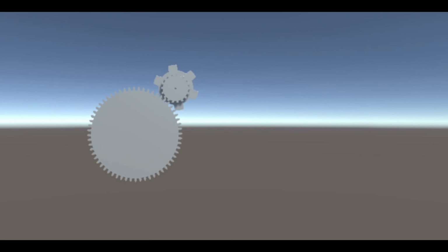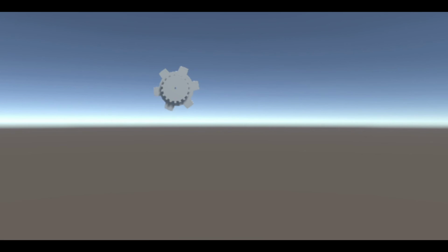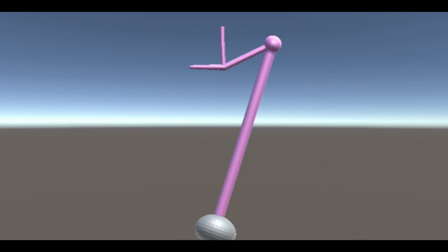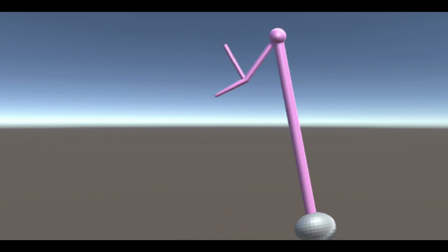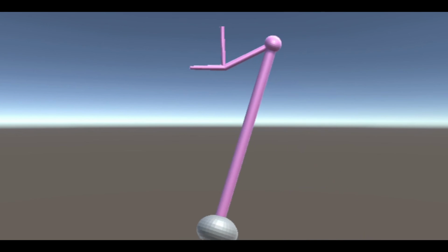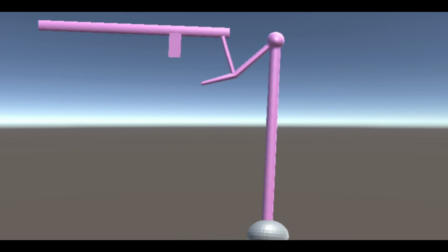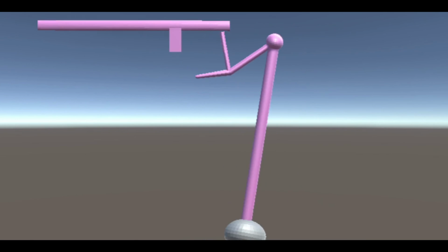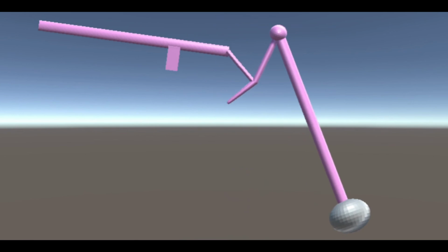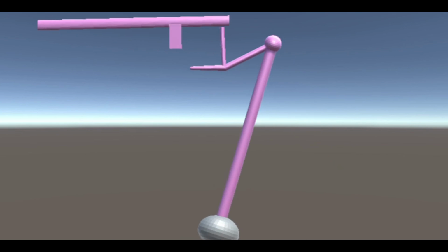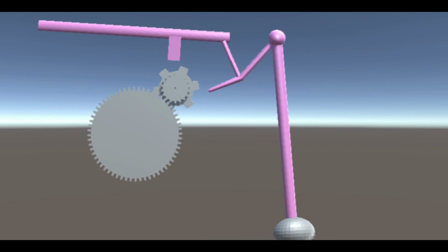Now, to control this mechanism and make it work with a fixed period, we add two little components, one pendulum and one escapement device. We use the pendulum to establish a simple harmonic movement that produces a defined time period for the clock to generate the characteristic 1 second movement to count seconds, minutes, and hours.